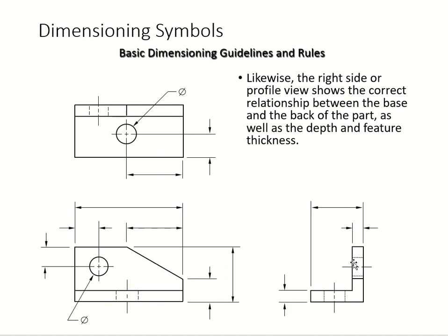The next one, yeah, smaller inside, larger outside, don't cross. Try not to cross over extension to extension or extension to dimension lines, extension or dimension to the object line, yeah. Leave one out, okay, and don't do the complete chain of dimensions.